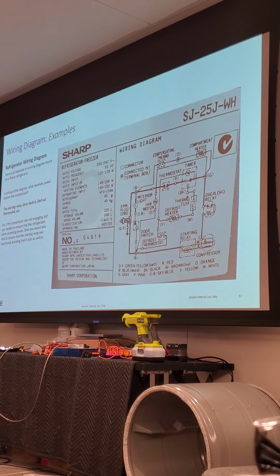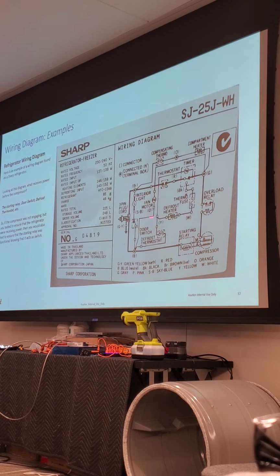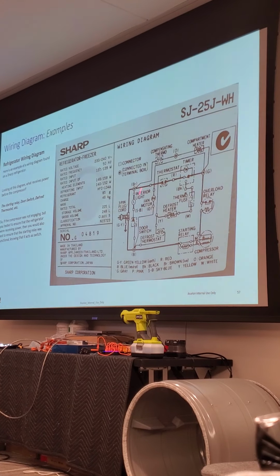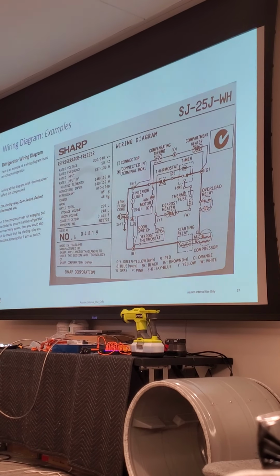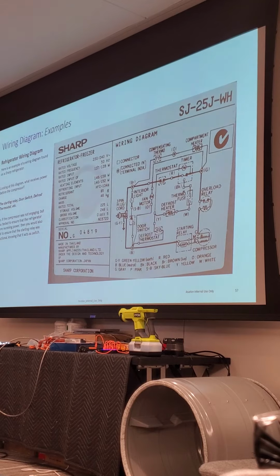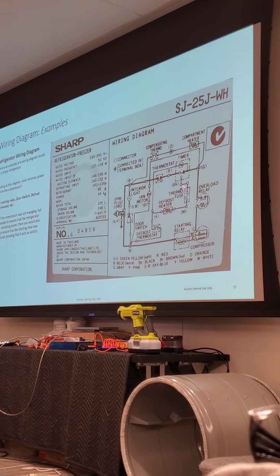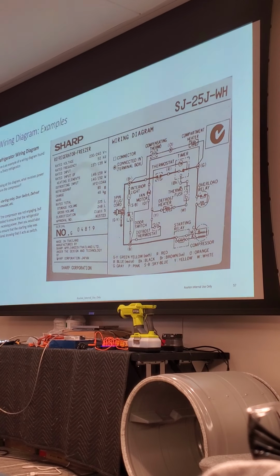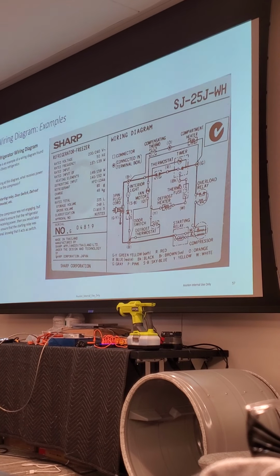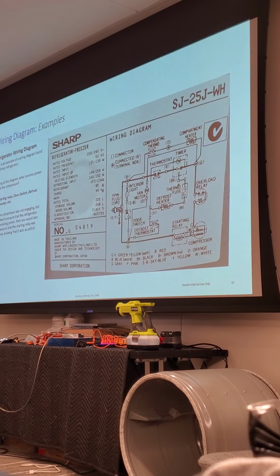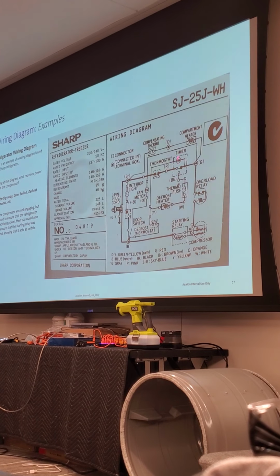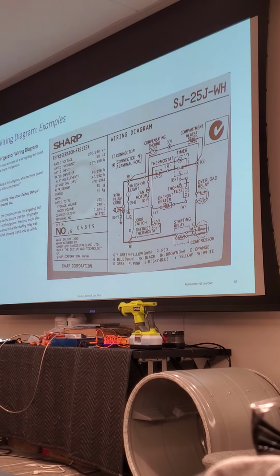Okay? And yes, the thermostat would be one of the things that you'd want to check. You'd also want to check and see if the fan's working. But just a real quick test, right here, right there, and right there would be the three things I would check first if that compressor's not working, because if that's not sending power to it, it's not going to work.